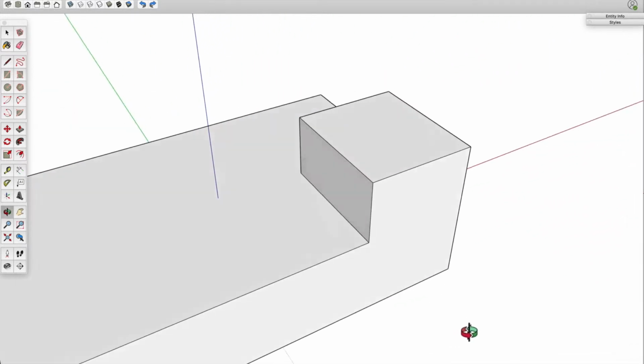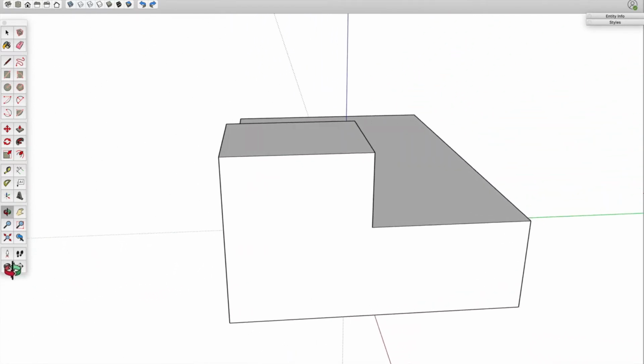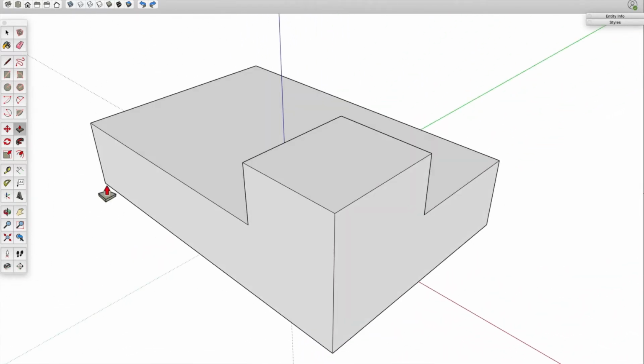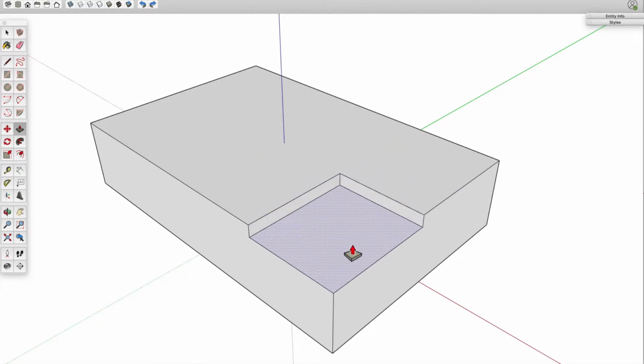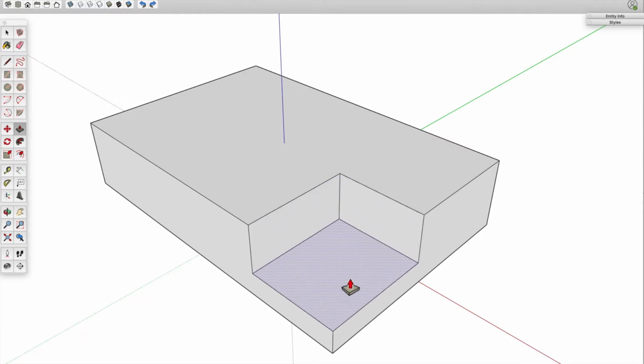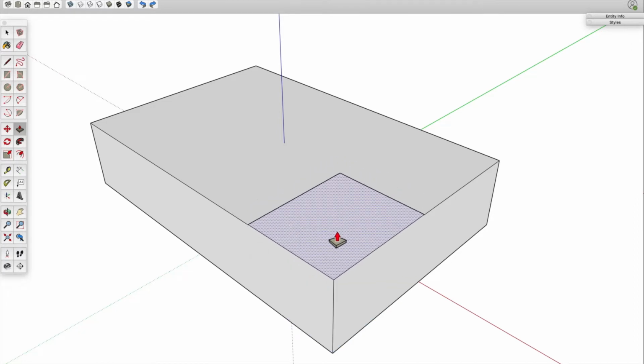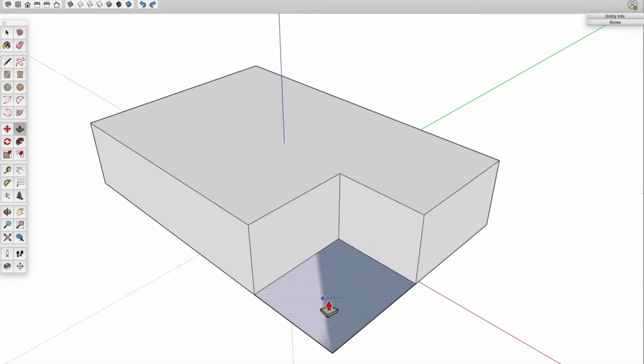And you'll notice that's an easy way to get some really cool new shapes going. Now try this. Go back to the same surface, click, and begin push-pulling down, so you start carving this away. Now move your cursor all the way down until you get this on-face blue dot, or you'll also see, if I move it back up and then move it down again, you'll also see that you have this sort of partially white, partially blue face. Go ahead and click, and you'll notice that it carves completely away, so it disappears.